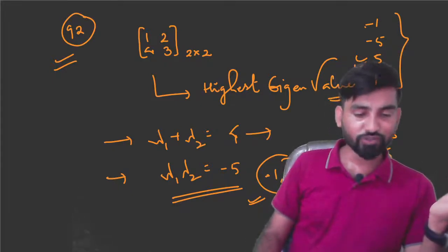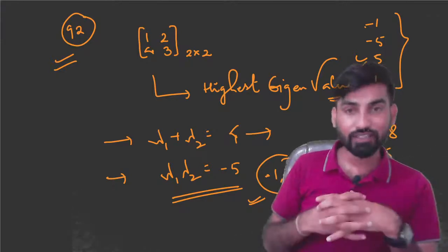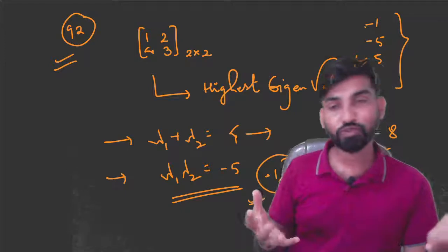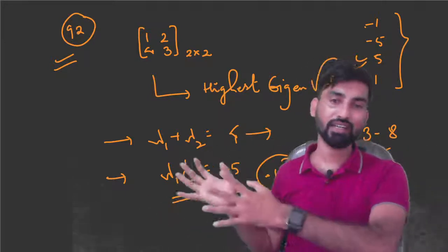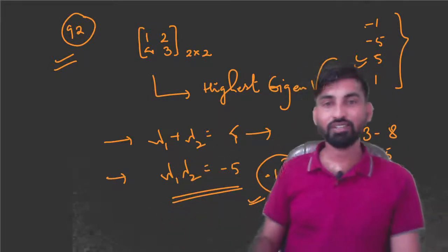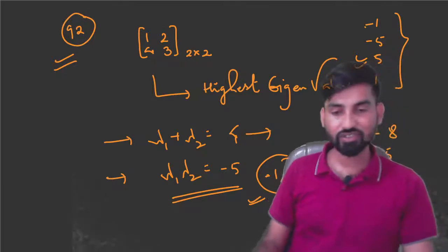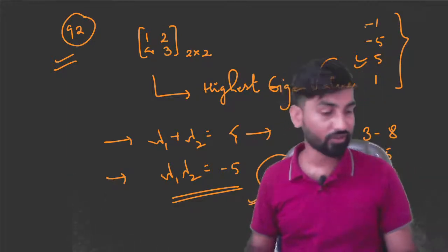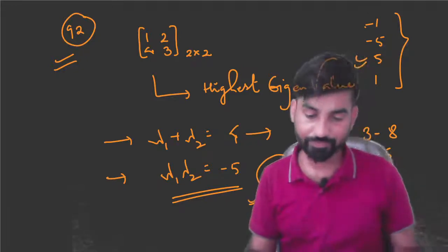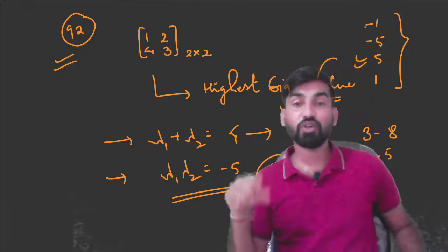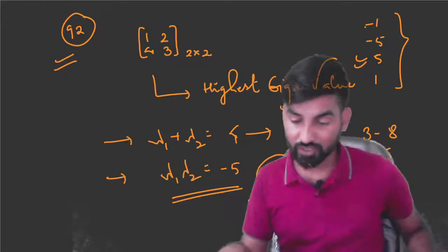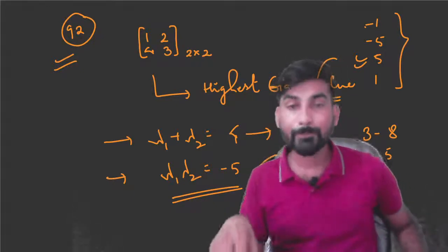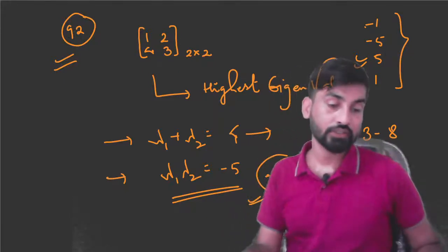And one question was on Z_TH. You have to find the Thevenin equivalent impedance, so what is the value? You have to deactivate or kill the independent sources, and then using series and parallel connections you can answer this kind of question. This kind of question was very easy. One question was from super mesh, which was also very easy, and a phasor question was there.